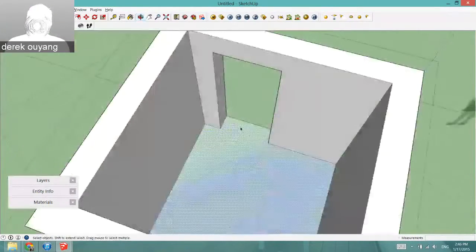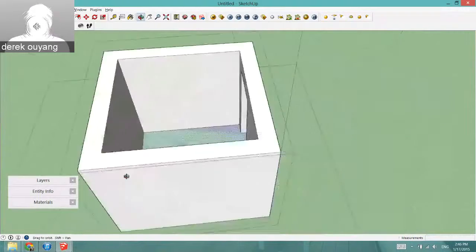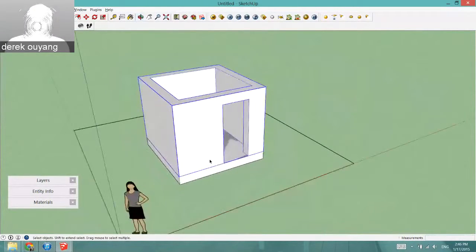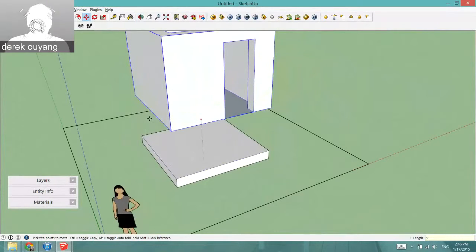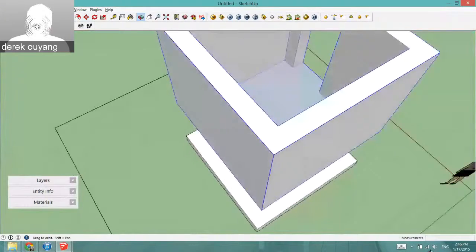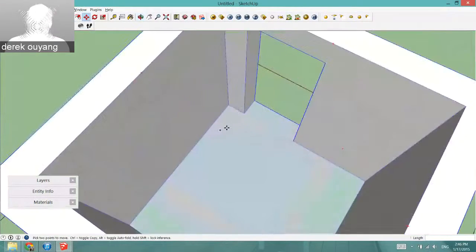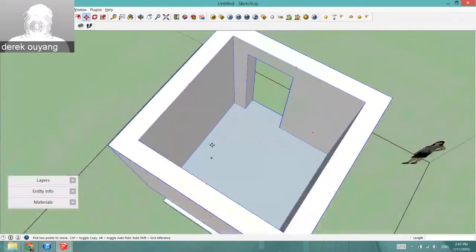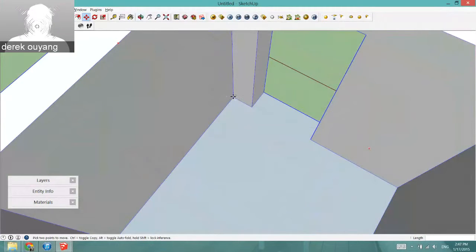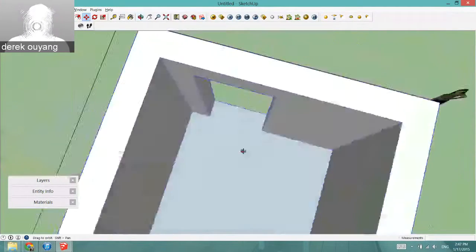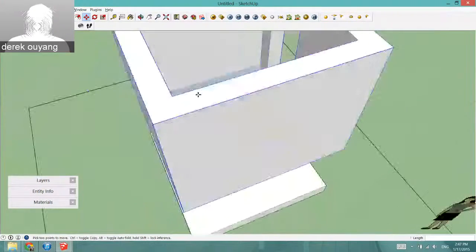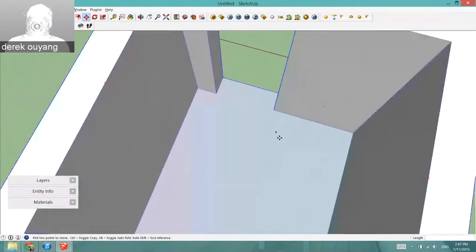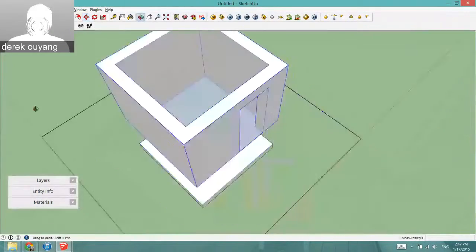Now notice one thing. There seems to be another surface now on the bottom of this, and we can confirm that if we moved the floor briefly off. Say we moved it upwards briefly 5 feet. Looked underneath, and it's actually created a new surface. Now, when did that actually happen? That happened when we made the guideline on the inside, because we had deleted the bottom surface, but anytime you reestablish a bounding shape, which in this case would be the inside square, then it sort of regenerates a surface. So that's something that I had just missed just now, and it sort of has bias in the process.